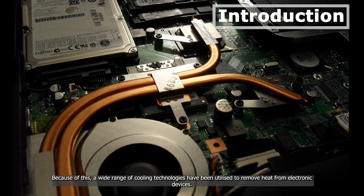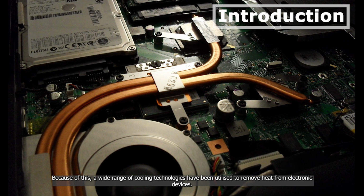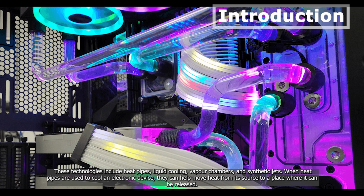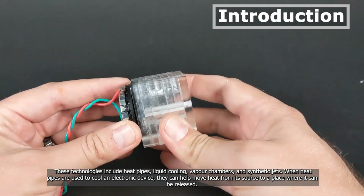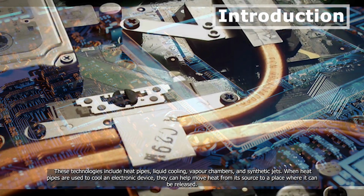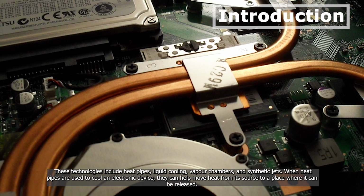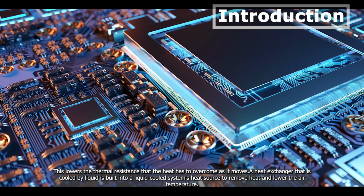Because of this, a wide range of cooling technologies have been utilized to remove heat from electronic devices. These technologies include heat pipes, liquid cooling, a vapor chamber, and synthetic jets. When heat pipes are used to cool an electronic device, they can help move heat from its source to a place where it can be released. This lowers the thermal resistance that the heat has to overcome as it moves.